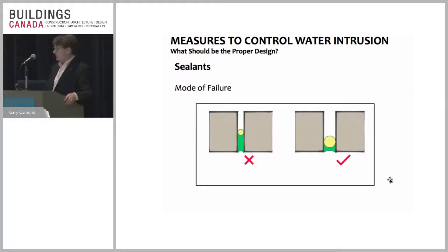I've got two shots here. The first one is a failure. Any sealant manufacturers here? It fails because of this thing called the hourglass shape. On this one, which is the correct one, I've got great bond there, I've got great bond there, and I've got a little bit of material here. That's correct, because as things move, where it's the thinnest, that's allowing the movement.